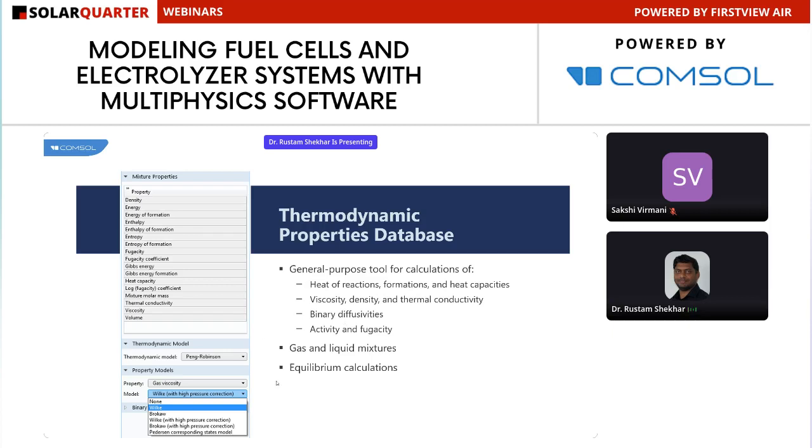So, for solving for these different properties, you can choose a model, where you can have different models for one property. In this case, we want to solve for the gas viscosity, which allows us to choose a model like Brokaw or Wilke and other kinds of models. It will have the gas and liquid mixture properties and the equilibrium calculations, so it will minimize the entries required to do that kind of modeling in fuel cells and electrolyzers.